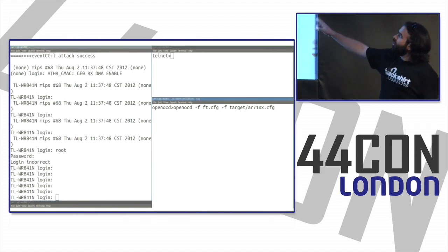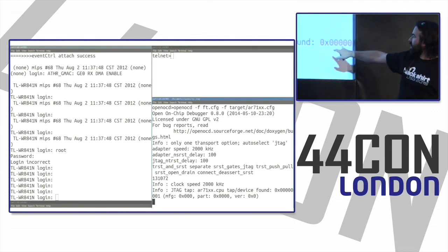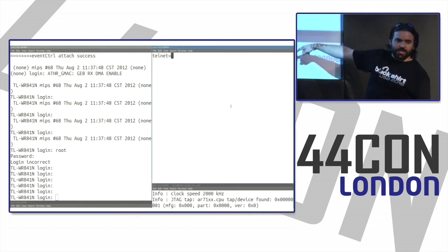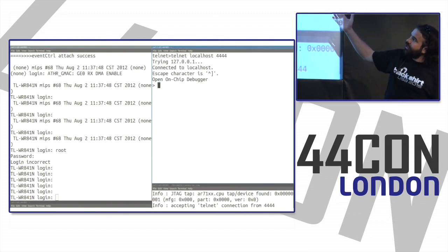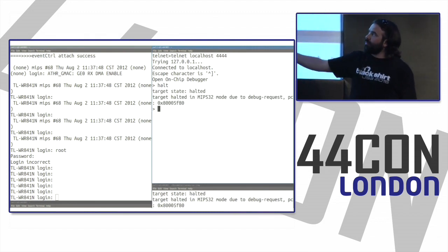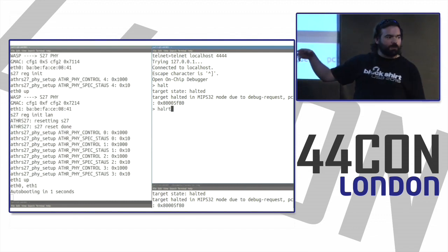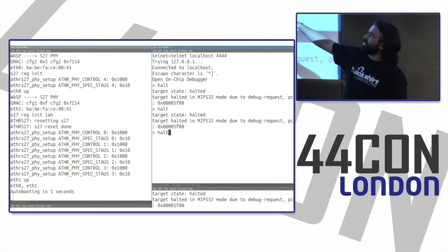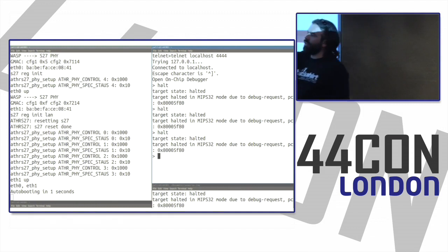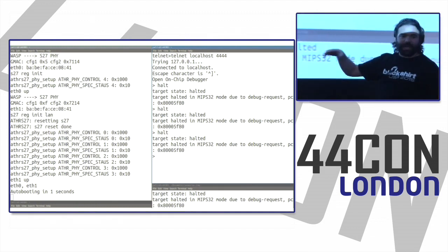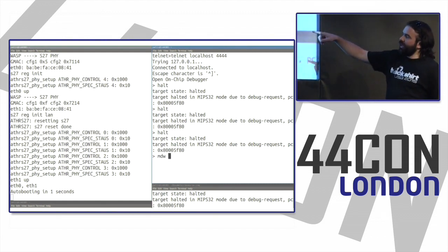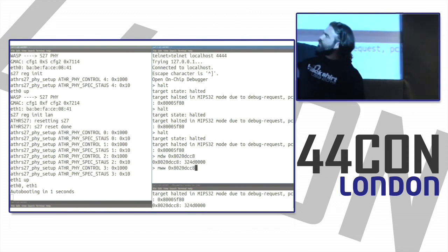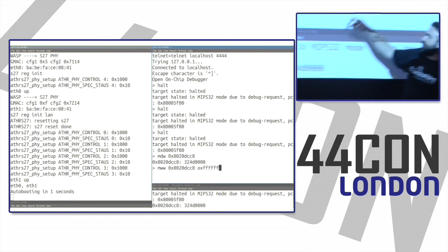And we go to OpenOCD. We'll start up OpenOCD. We have a config file for the target, and it starts up. It found our device. It tells us the ID code. I'll go to Telnet. This is connecting to OpenOCD again. I tell it to halt. It stopped. This device has a watchdog timer, which means if it sits idle for too long, it restarts. So I halted it, and then it started again, and I wasn't fast enough typing halt again, and it restarted again. But now I hit halt, and it's still really early. It's still in the bootloader, so it hasn't turned on the watchdog timer. So I can now go and look into memory. This address I calculated based on where the kernel gets loaded and the offset, and I see the 324D, which is the last bit of 32M, and then null strings.